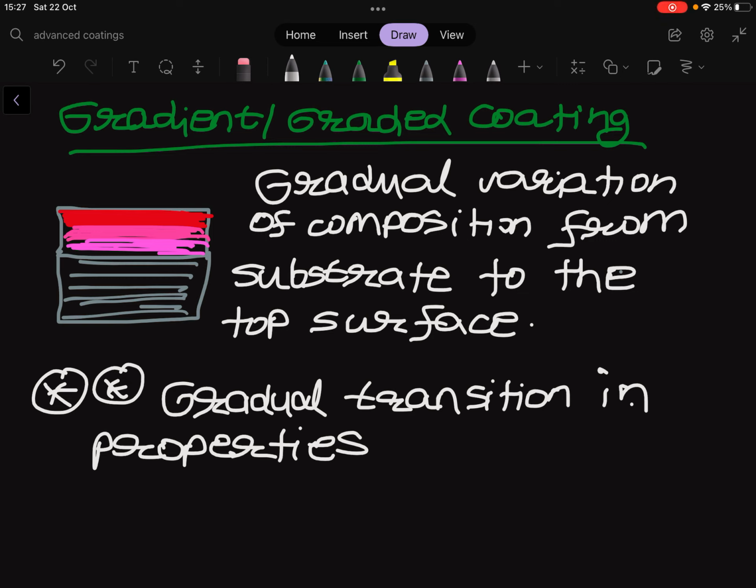So how can we produce these gradual coatings? As we mentioned, the most typical method is the generation of nitrided or carburized profile, because we have a gradual variation of the nitrogen or carbon content moving from the surface to that, and we have corresponding hardness gradient. So it is possible to generate this variation over a larger depth, so it is most efficient way. We can produce graded composition in PVD technique. We mentioned, for example, production of nitrides as wear resistant coatings.